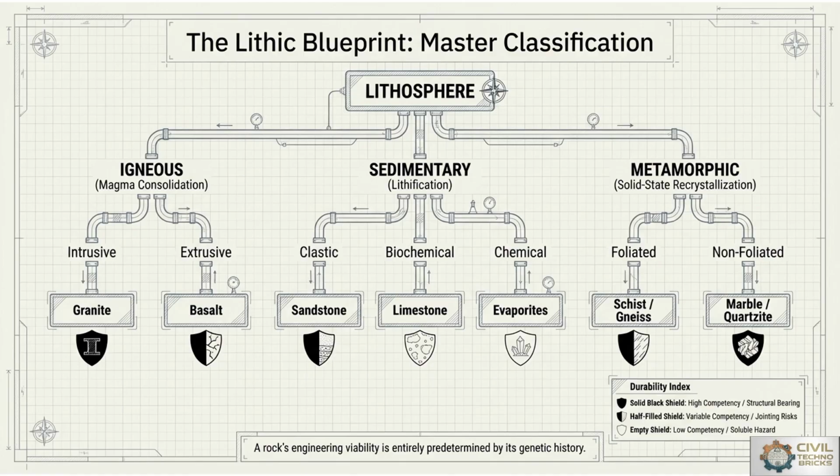Basically, from the engineering point of view, we have to check the suitability of rock for site selection criteria for any structure, or the foundation characteristics, which depend on the rock origin, the texture of the rock materials, the minerals present within the earth surface, geological explorations, and all other weathering characteristics due to external or internal factors, just like tectonic forces, groundwater, or any fossils which are available within the rock layers.